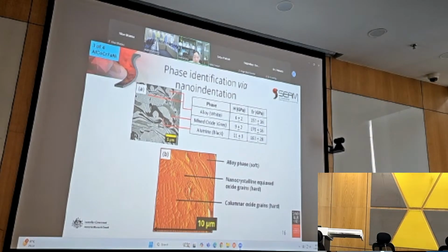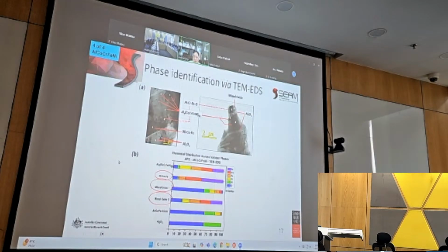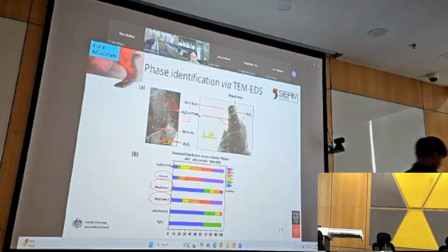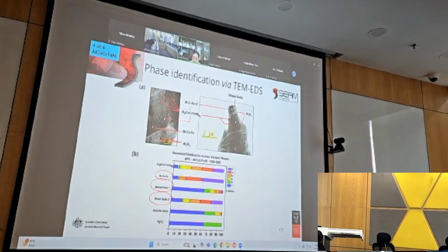It was in the paper that we explained what actually happened, and that was very good, because we are now able to look at how the elements flow within the melt pool, in the metallurgical sense, or as it quenches, and then explain the phenomena of how the coating evolved.